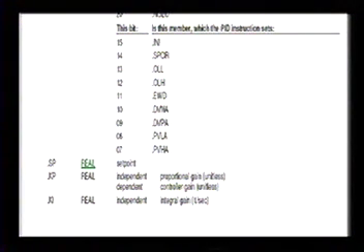So your set point would actually be PID1.SP. So if you had an OIT man-machine interface or InTouch or an HMI type system, and you had an operator type in a PID value, they would take that value and do a move command into the PID1.SP, right? And so that would actually move that variable into this instruction.